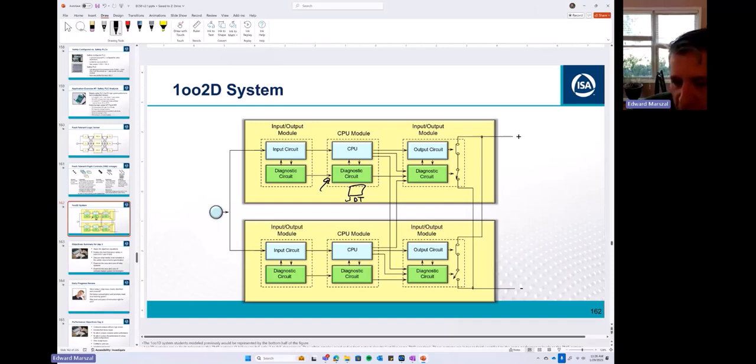And not only are they going to have it, they're going to have redundancy: watchdog timer 1, watchdog timer 2, 1 out of 2 vote. When this watchdog timer detects a failure, they will communicate to the diagnostic circuitry to open that circuit, basically to de-energize all the power out to the field.